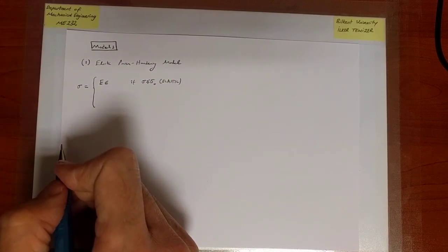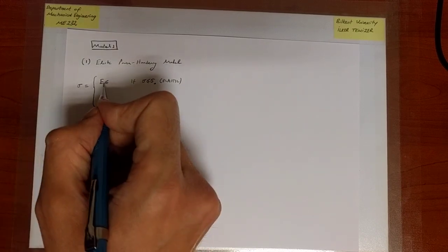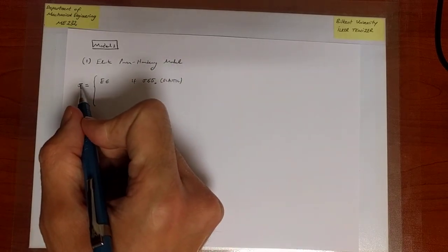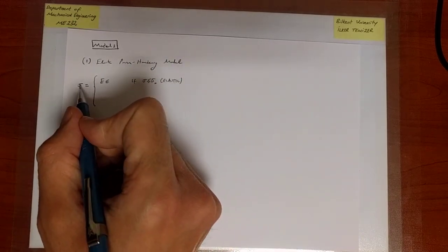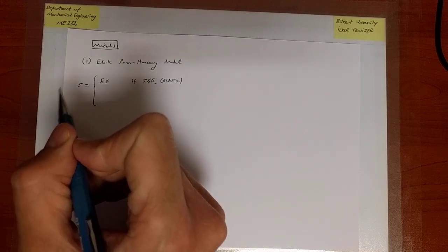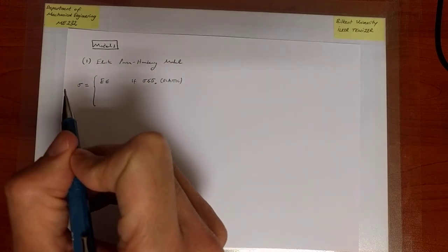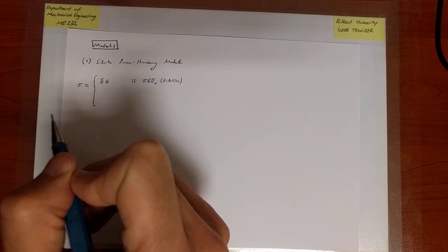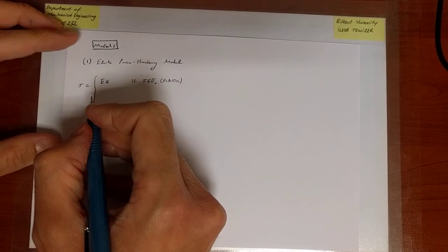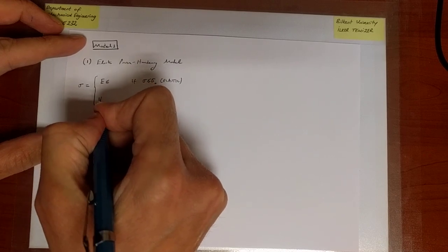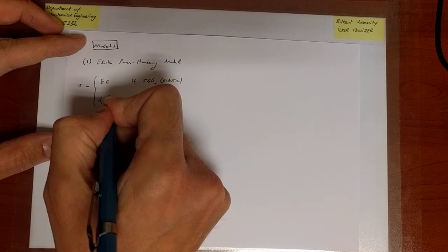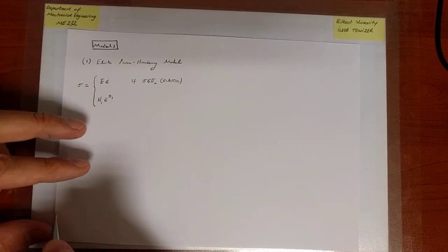Now, if I'm in the plastic region, the stress is not a constant anymore, and it's not equal to E epsilon because it doesn't change linearly, it's not a straight line at least, plus it is continuously varying in magnitude because the material hardens. So what I want to have probably is some simple relation that is able to capture that, and the simplest thing one can think of is a constant times the strain raised to some power, and let's call that power n1.